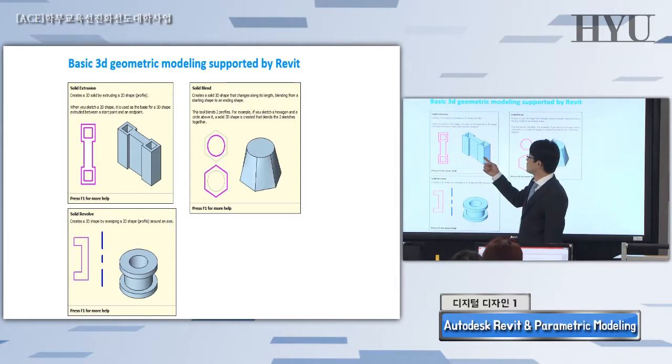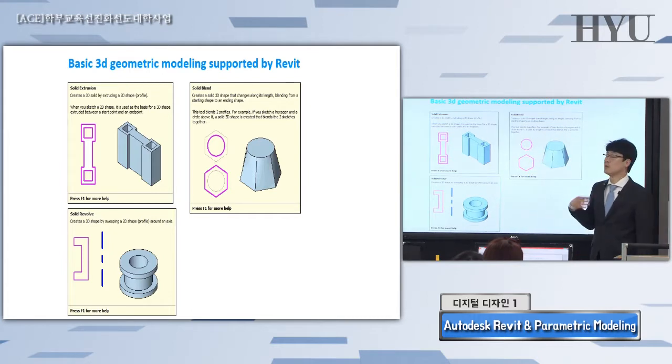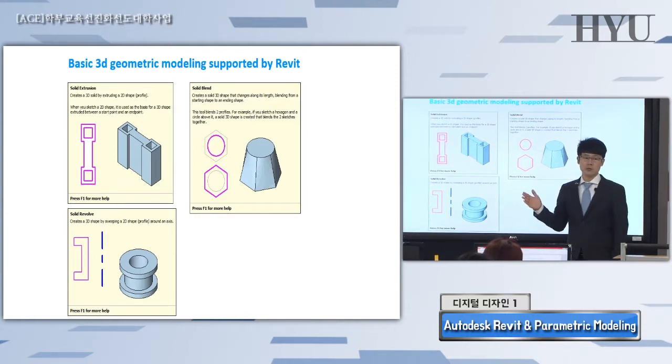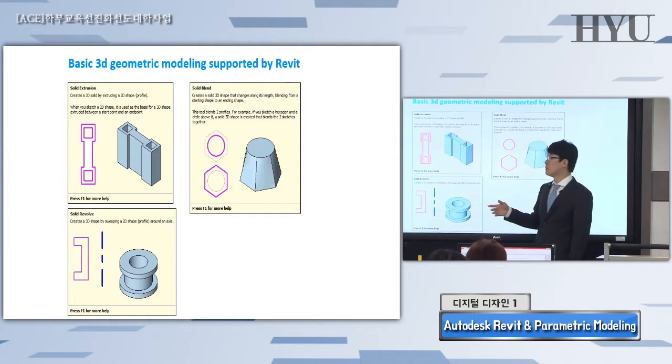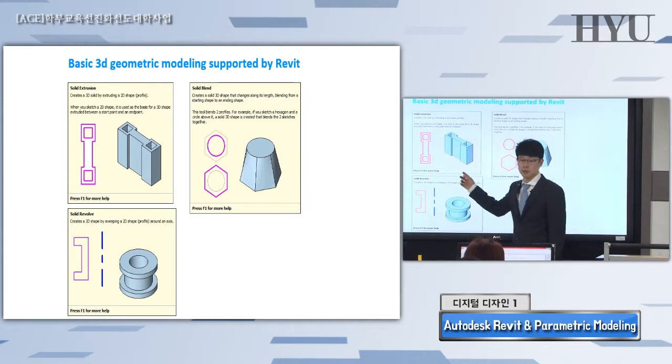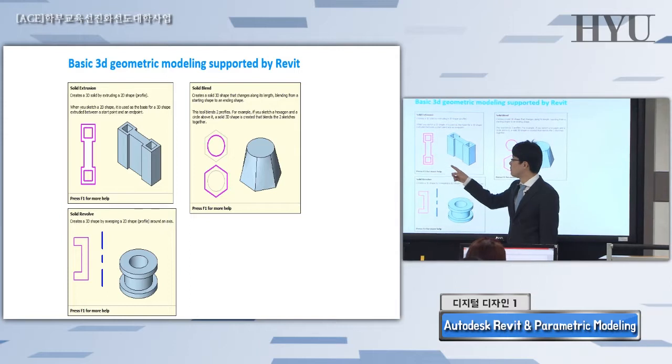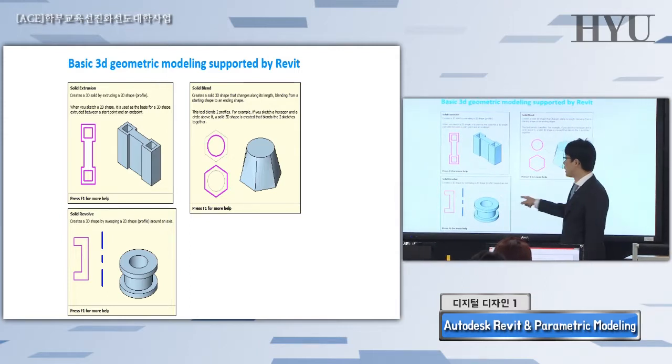In other words, even if they look totally the same, technically, in terms of the technology behind them, they are totally different. But actually, in Revit, you couldn't find such modeling icons because it's kind of a project management tool. But in the Revit family editor or customized sketch editor, such as sketch mode for drawing some object, drawing a floor, you can find something like this. When you draw the floor boundary and click the create button, the specific thickness is added and the floor slab is created.